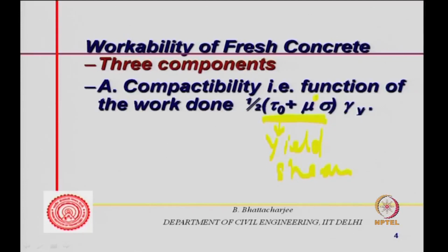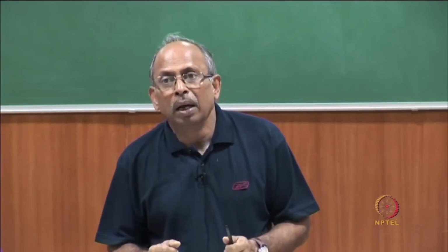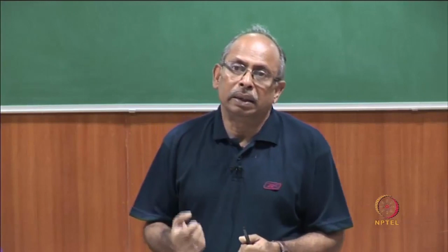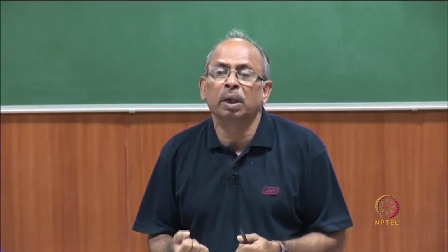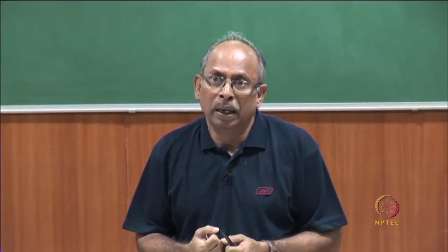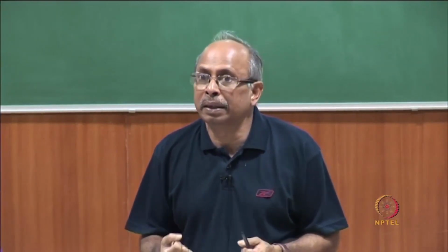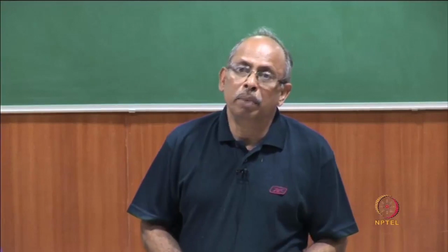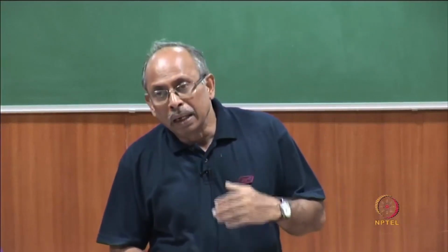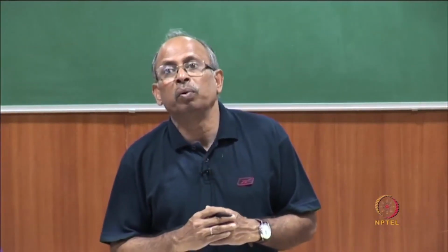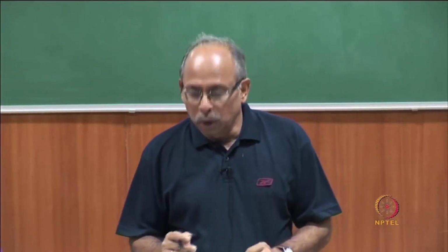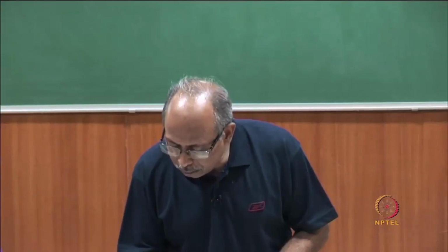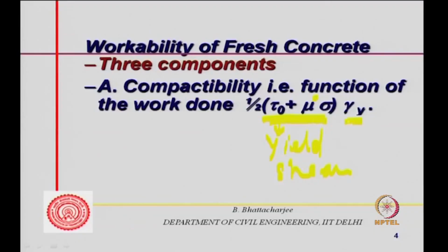If we do a box shear test, we would see that the stress strain curve is a function of the normal stress that we apply, the shear stress it can resist, and mu is a kind of coefficient of friction or viscosity, the dynamic or plastic viscosity. So, stress would be this, and this is the shear strain.